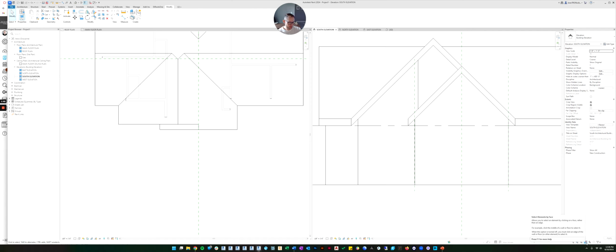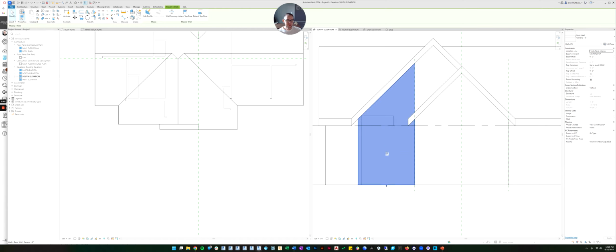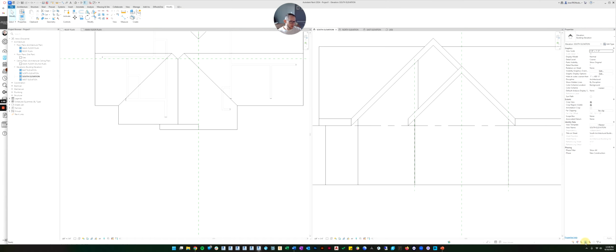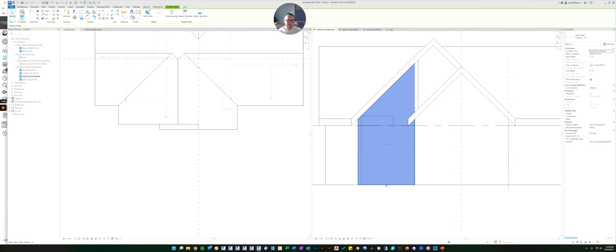You have to pick the edge. If you click that, it'll take the X away, and now you can select the face of the wall. Sometimes that's helpful. Sometimes it's not what you want, and so you shut it off. But right now I want it on, so let's click the face of that.